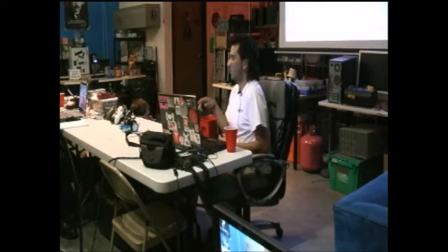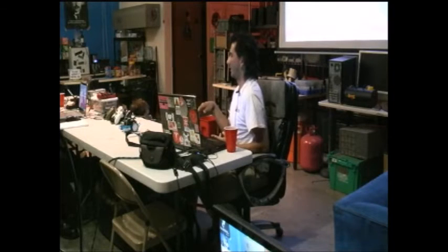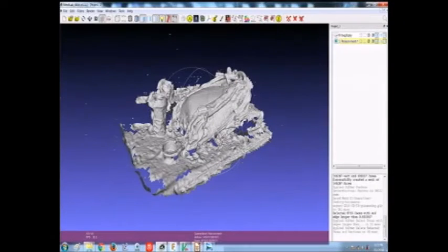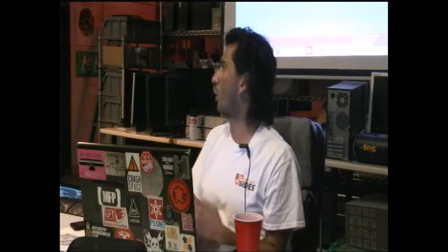The one very bad thing to have in a resulting mesh file is long, skinny triangles, because when you're applying trigonometry to long, skinny angles, you sort of round off a lot of decimal places. You end up with a noisier, not as accurate result. So by refining the edges here, we're trying to get the highest quality edges with the most equilateral triangles, which you can apply more robust math to.